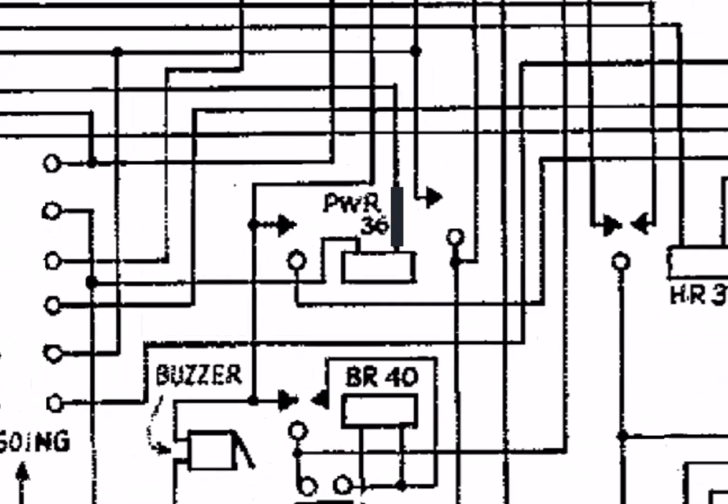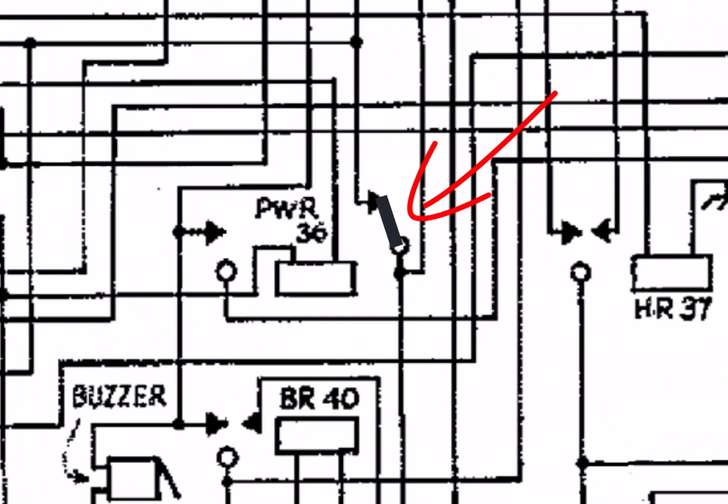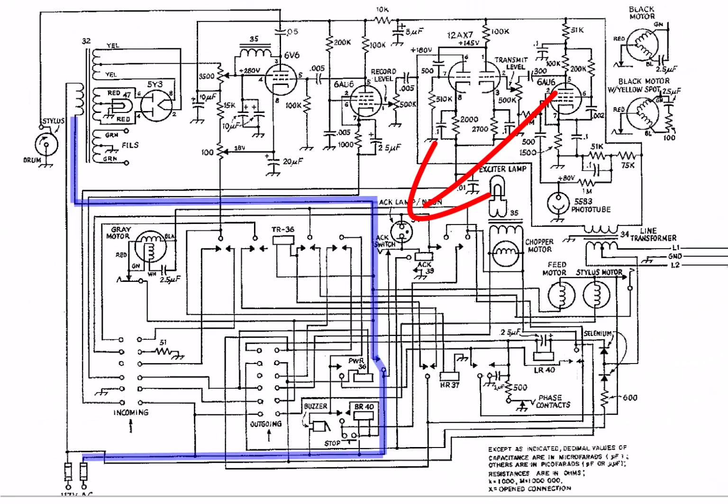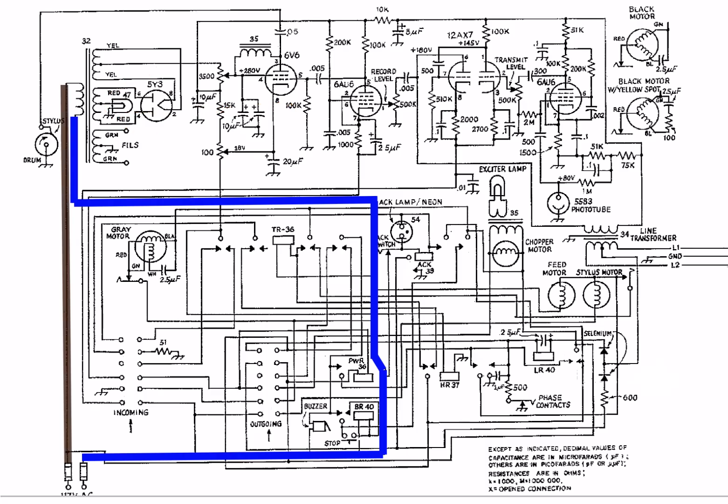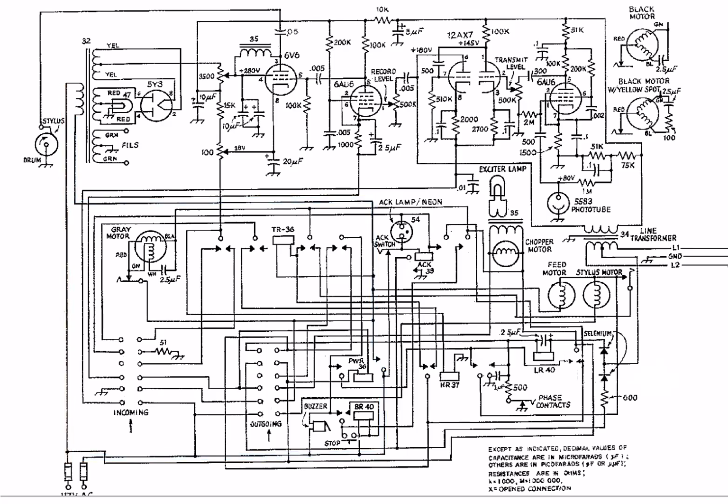So again, that relay closes when either button is pressed, and that happens no matter what else is going on in this circuit. So if either button is pressed and the main power supply relay closes, then this switched leg of the power is applied to the main amplifier power transformer, and the other line input is directly connected to the power input, so the amplifier begins to power up. And again, that's no matter what else is going on in this device.